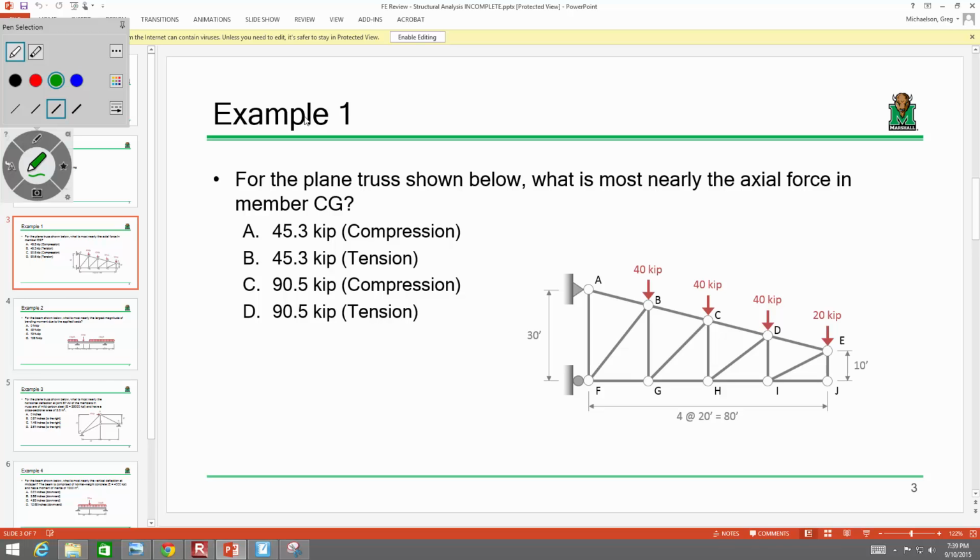Now, if you do enough truss analysis and get familiar with that behavior, you can recognize that because the diagonals are facing this way, they're going to be in compression. If the diagonals inside were going like this the other way, they would be in tension. And it just comes from doing enough truss analysis that you start to see the patterns. But the easy ones to see are the top and bottom members.